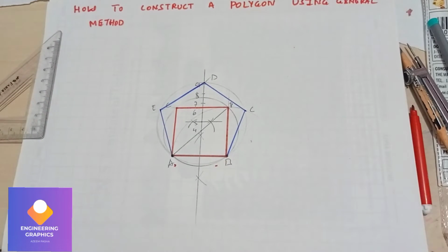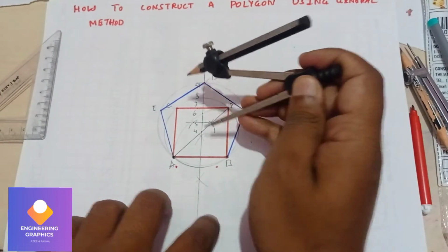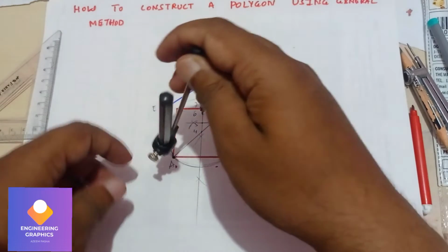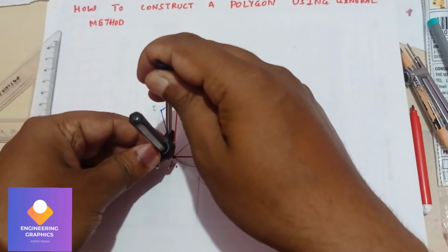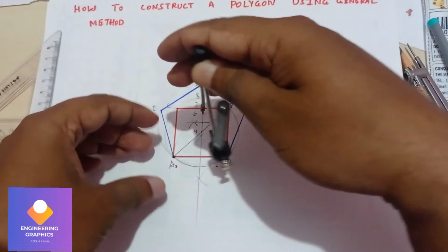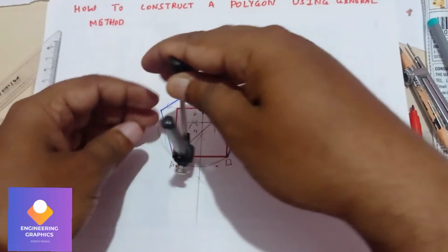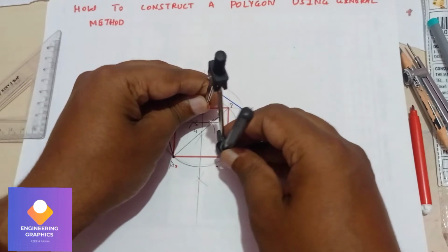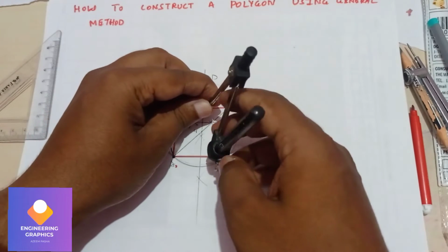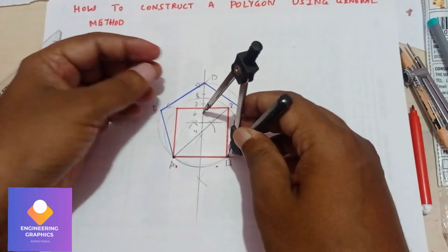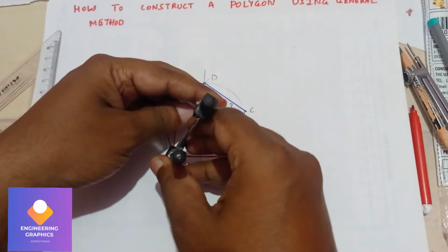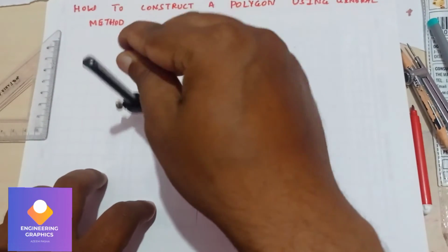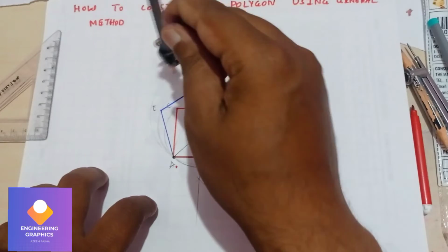Now in the same way we construct the hexagon. Measure the length from 6 to A, point 6, and measure till A and check it out with B. It's not matching, so you need to be careful. It should match with both points A and B. You should check it out and then you draw. A little bit of difference, as I mentioned, will not give the exact shape.